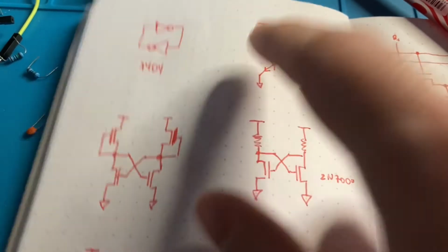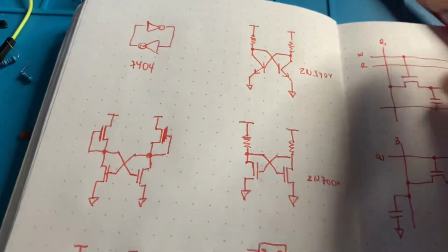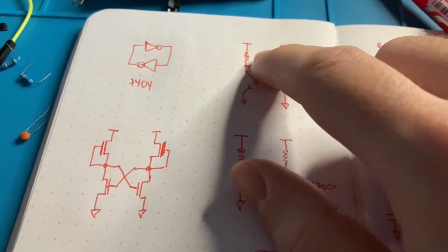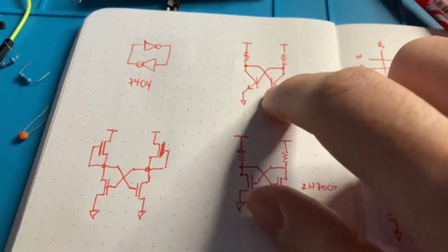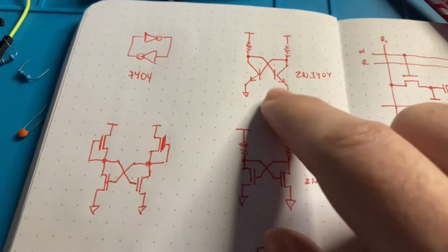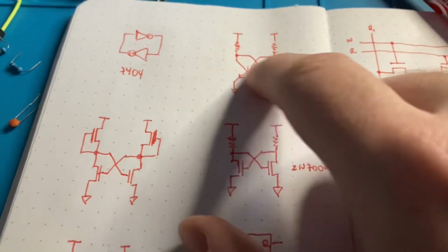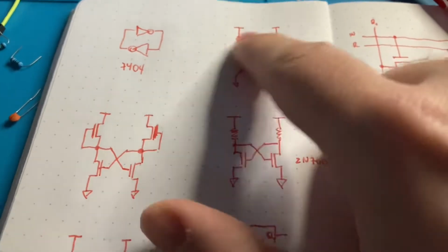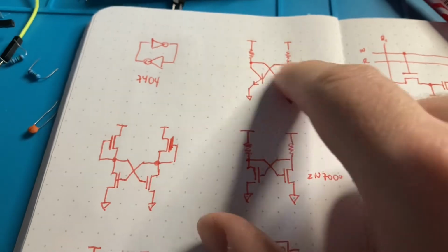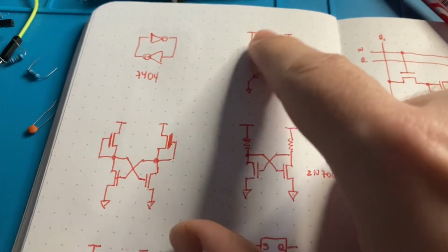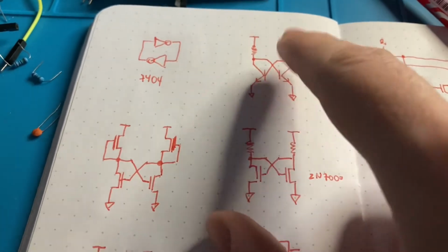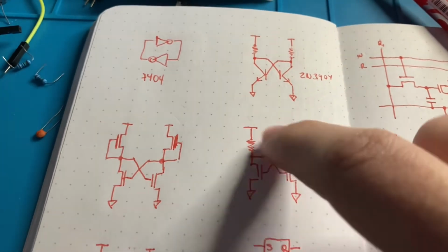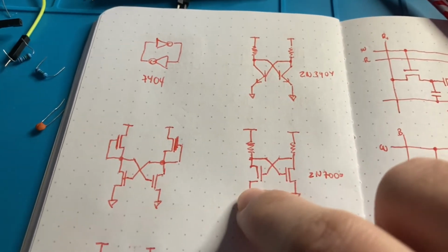I think, yeah, that's where you do the math. V equals IR, and then you get I equals V over R, and you see how your project will consume a lot of energy just on standby, because you always have a resistive path consuming current.